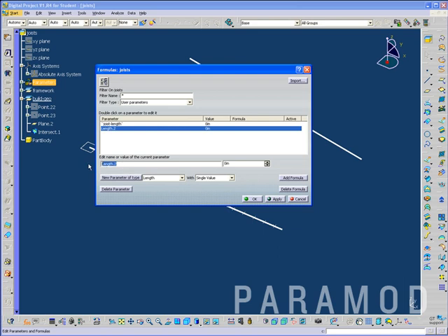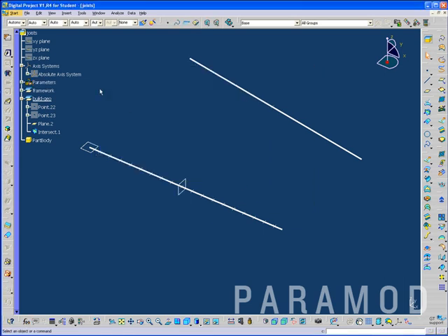But if we do this again, we say joist_length or something else and say apply, we don't get those single quotes. So I'll probably be using underscore from now on. But the second one that I'll make is depth. Both of these of type length. So I can say apply and say OK. I do want to delete that first joist length.